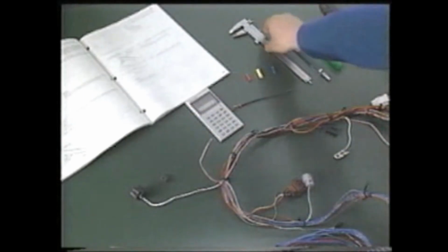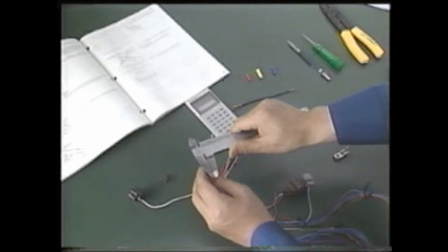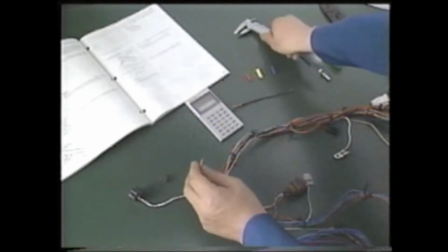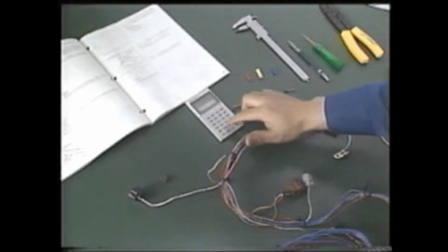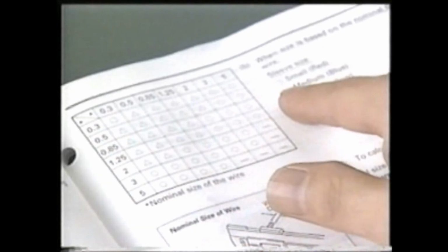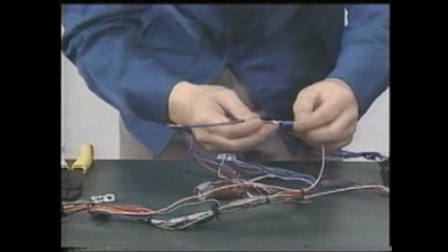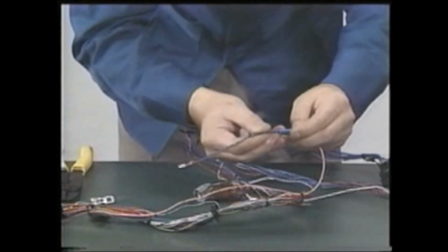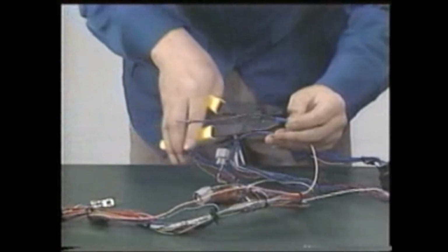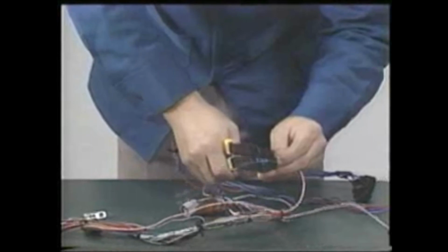The thickness of the wire attached to each supplied terminal is unique. This means that other wires joining it may have a different thickness than existing wires. After confirming the nominal size, you should consult the chart we looked at before to determine the sleeve size. When carrying out repairs, be sure to work carefully to prevent breaking terminals and connectors and to prevent faulty wire connections.